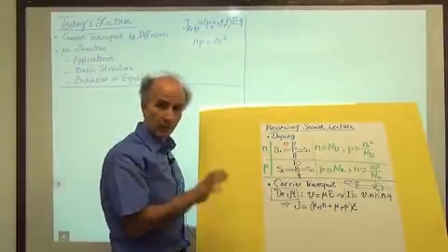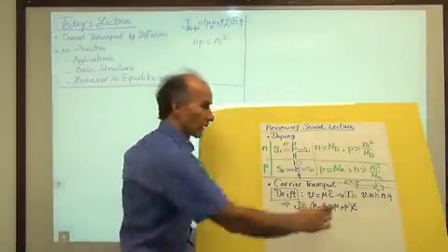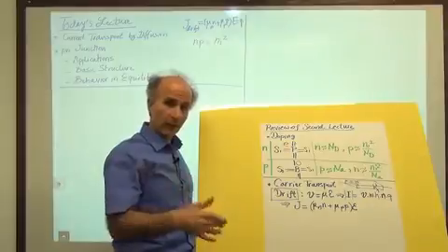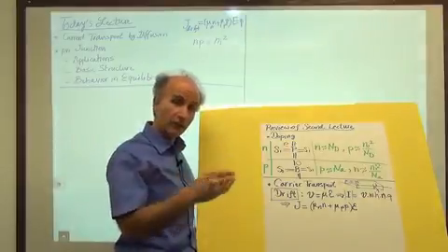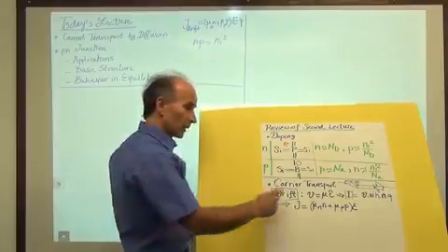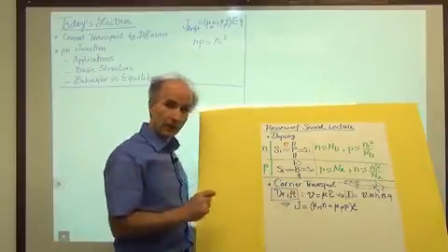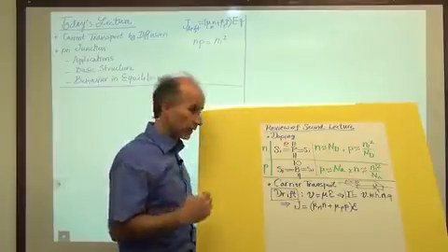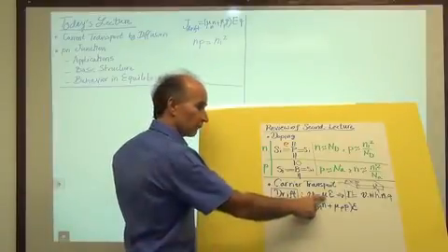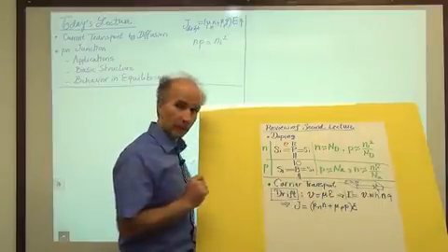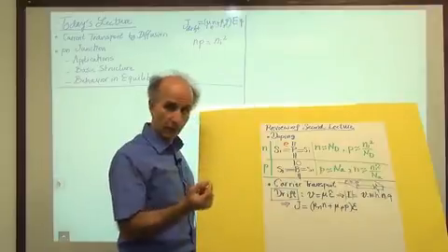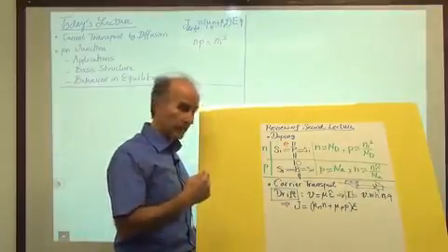Drift simply means we apply voltage across the semiconductor, and that creates a current because we have created an electric field inside the semiconductor. For semiconductors, the velocity of carriers, similar to a parachuter, reaches a terminal velocity and is equal to mu times the electric field, mu being the mobility of the carriers, electrons or holes.